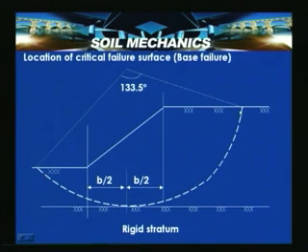That circle is assumed to be the critical failure surface, which is tangential to this. The condition is that it is tangential to this, and with that condition, once you draw the circle along this vertical line, that will give the critical failure surface. So, we looked into this procedure, a very empirical procedure available for locating the critical failure surface.